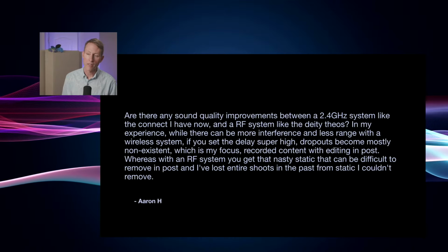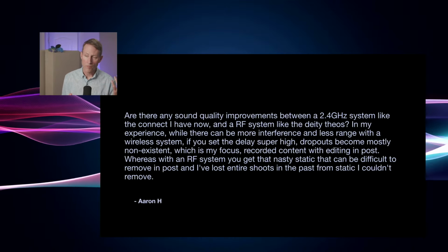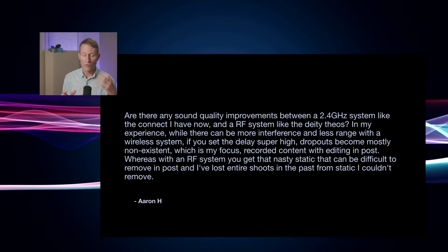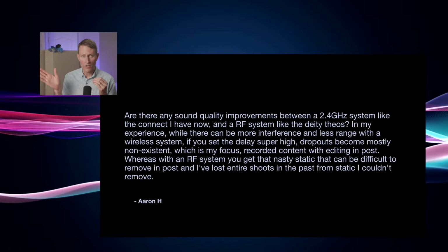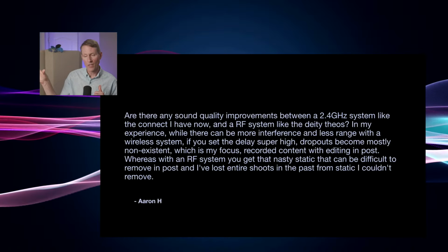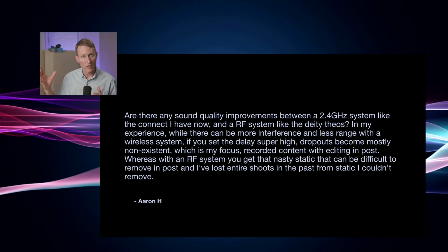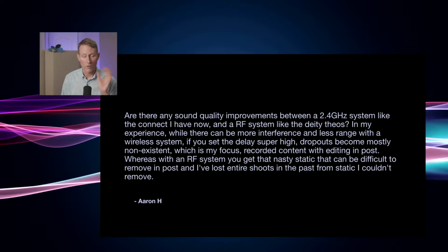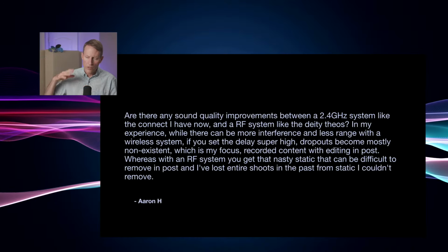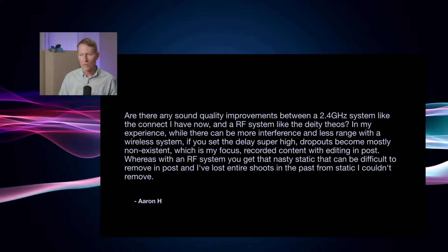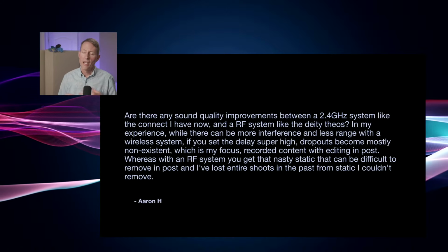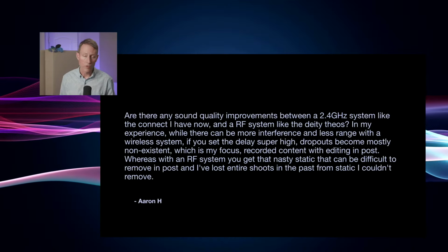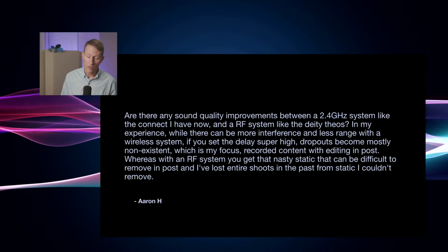But on the other hand, Aaron, with the Theos system, you can record at the transmitter pack outside of the United States. You can record at the transmitter pack and transmit at the same time. So you could use your transmitted audio as sort of scratch audio or a sync reference, and then go back to the original very high quality audio that was recorded to the transmitter pack. The wirelessly transmitted audio has some odd things that happen in the higher frequencies. It's debatable whether it makes the audio unusable. I don't think it's unusable. It depends on the circumstances.